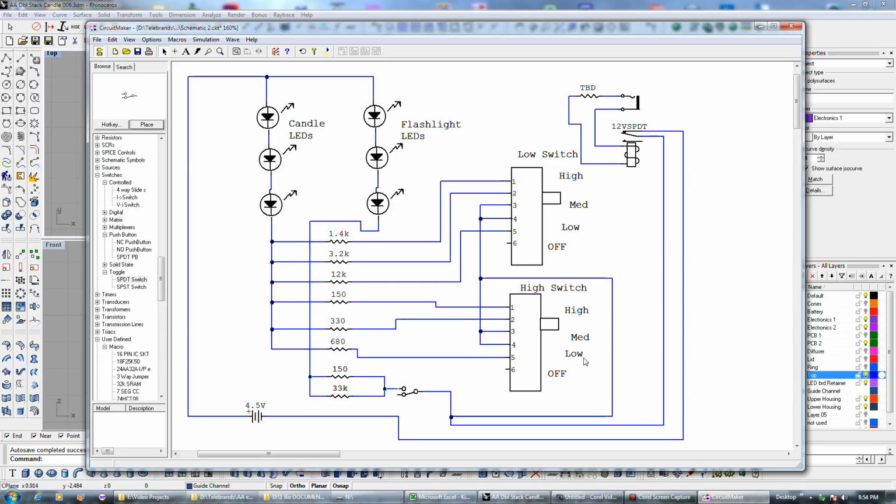But what I'm playing with is the idea of putting this relay and this power jack in it. And what that means is you can plug a power supply, any power supply, any wall pack that's a 2.1 millimeter jack, which is a common jack. You can plug into this anywhere from about 8 volts to 24 volts, and what it'll do is it'll turn this relay on, and when it does turn the relay on, that actually opens the circuit.